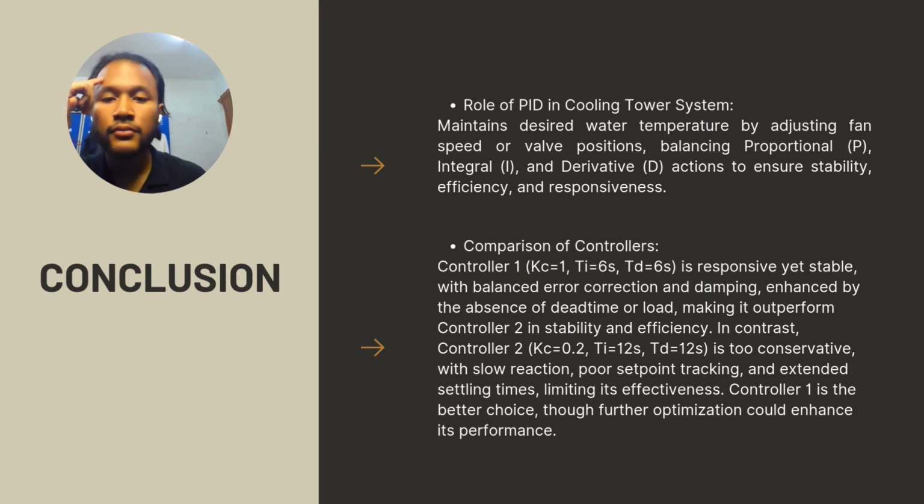And second, comparison of the controls. Control 1, with KC 1, TI 6 seconds, and TD 6 seconds, gives a responsive yet stable result with balanced error correction and damping, characterized by the absence of dead time or load, making it outperform control 2 in stability and efficiency.